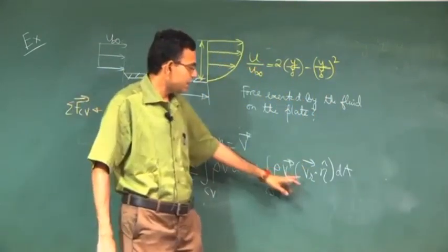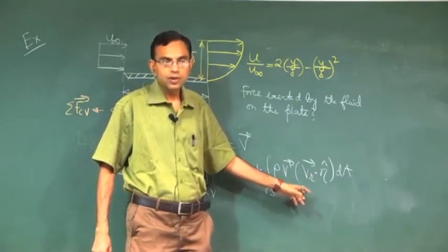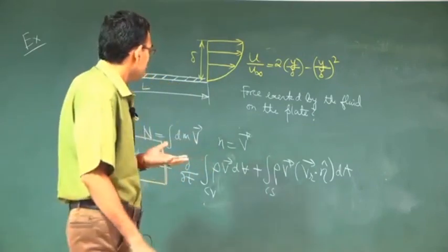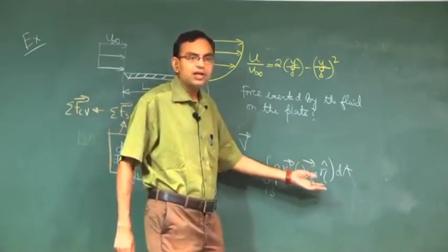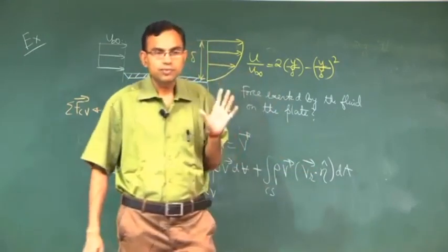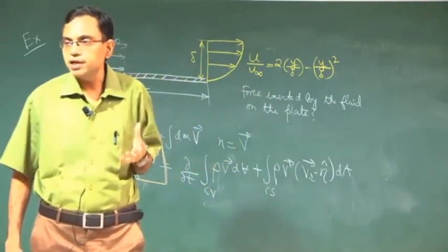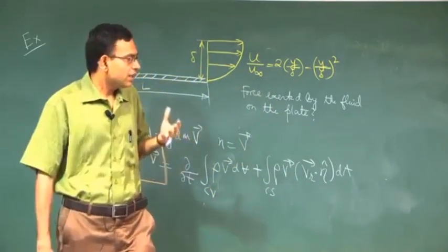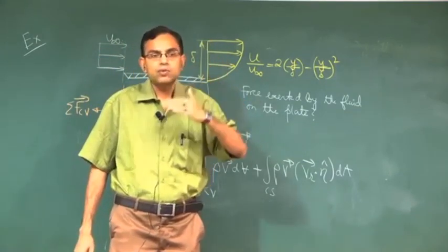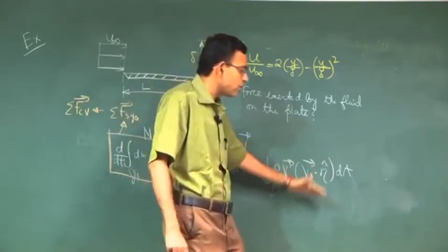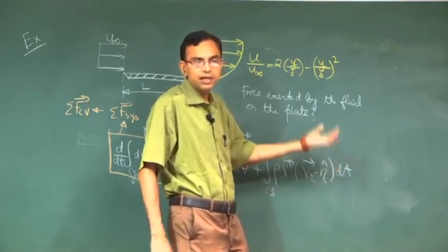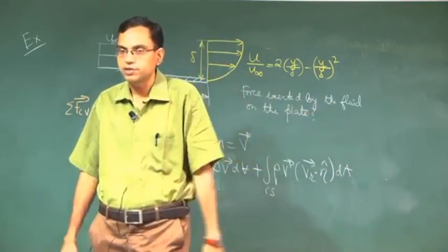Sometimes this is called the momentum theorem. In fluid mechanics, in various texts, typically at the undergraduate level, this is not derived and is just introduced as a momentum theorem. But I believe that Reynolds transport theorem being the most general one, no matter whether it is mass, momentum or whatever conservation, it is better to follow from that. I do not mind if this is called the momentum theorem, but it is fundamentally Reynolds transport theorem applied for momentum conservation.